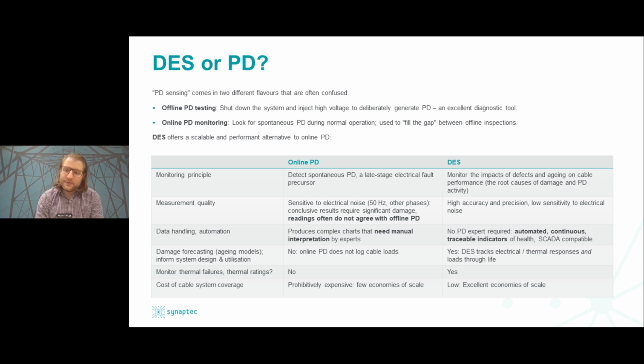And that's the key point: when you do it offline, when the cable is disconnected, then you can ramp up the voltage to typically about 3 times nominal voltage. And then you can really stress the asset and find if there's any weaknesses. But obviously, once the system is operating and has been commissioned, the voltage that the cable is exposed to is going to be nominal most of the time, apart from during any surges or switching. So that means that partial discharge has limited value during online scenarios, which is most of the asset's lifetime.